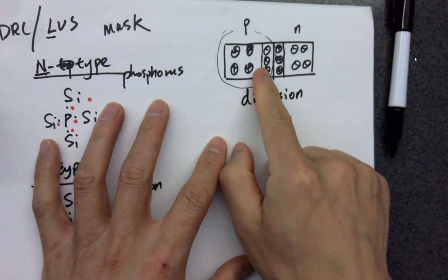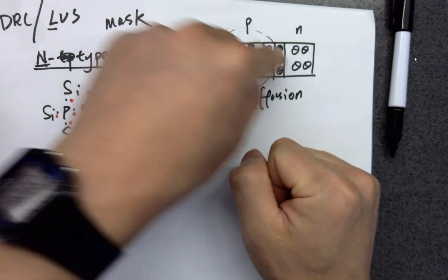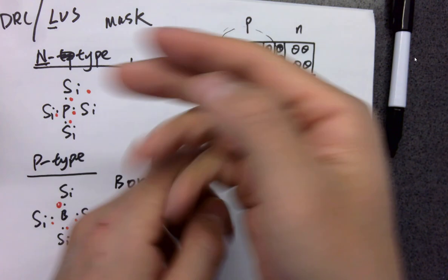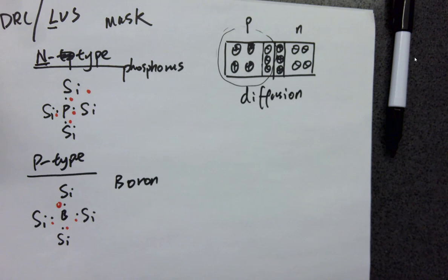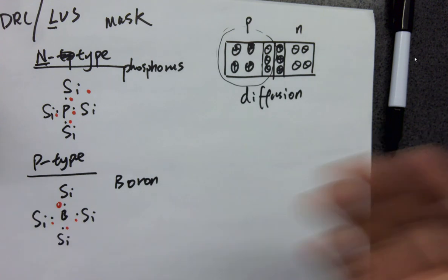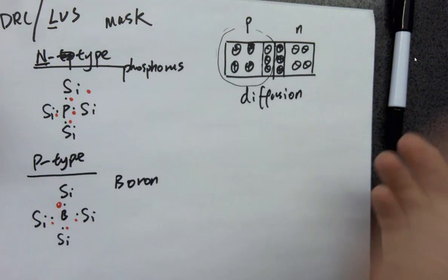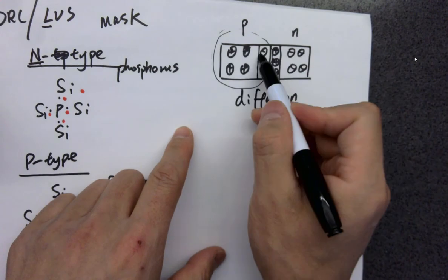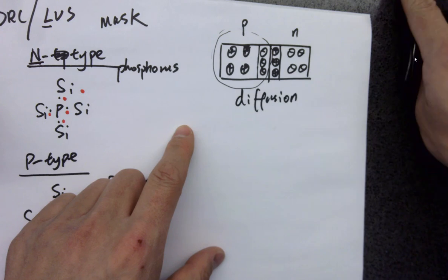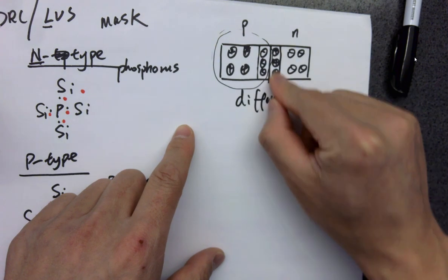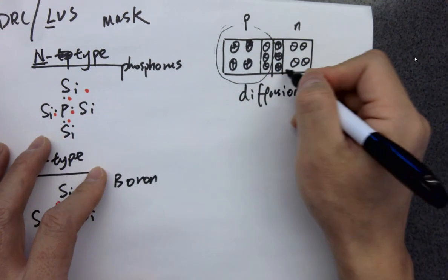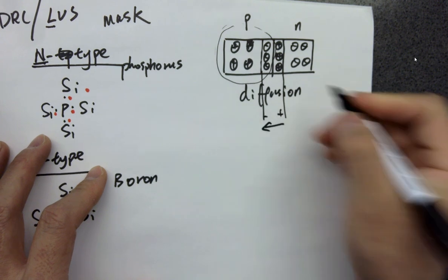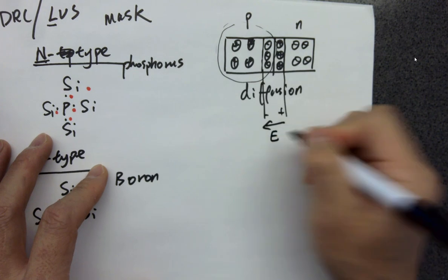because of the concentration gradient, the holes will migrate to the right, but actually it's the flow of electrons going away that leaves holes in there. But we just explained it as the holes going to the right. Actually, holes are not moving, right? Just keep that in mind. So we just imagine the holes are moving to the right to form a positive charged field. So eventually, these two pieces are forming an electric field, because plus and minus, right? So the electric field is pointing to the left.